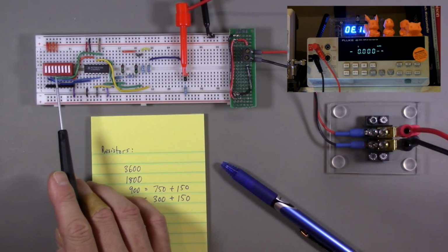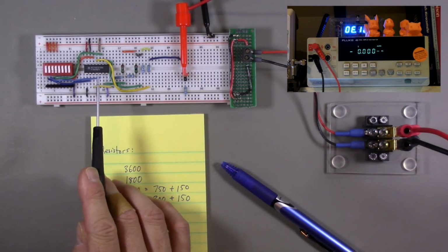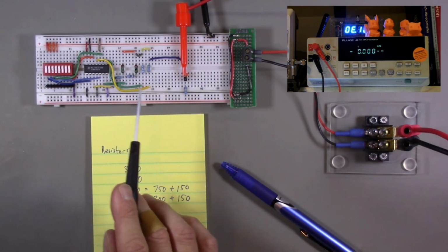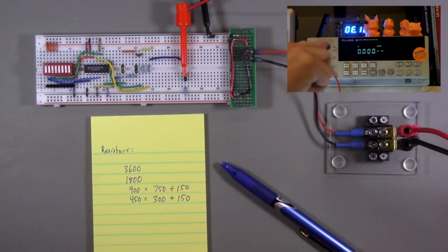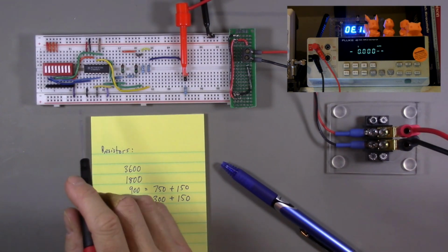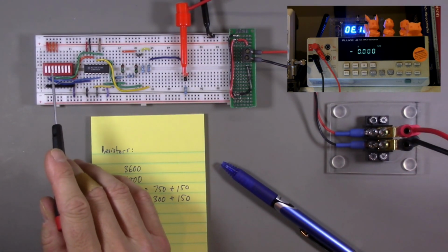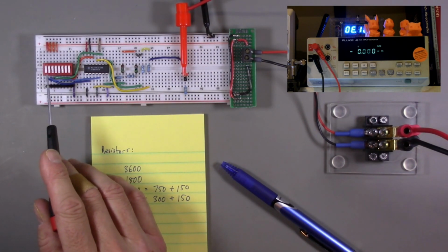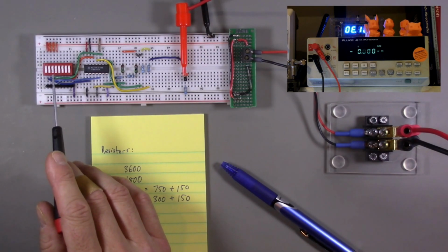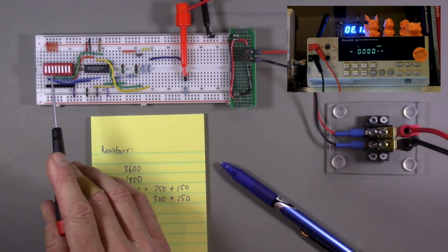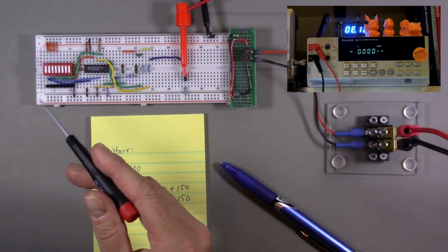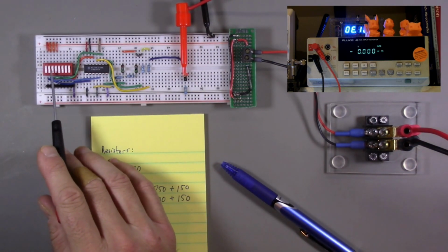And based on the combination of inputs and the combination of output voltages generated, I should get an output voltage here that I can read on our Fluke 45 multimeter here. And essentially what I'm looking for is that as I select various binary values here, I should see appropriate voltages generated, and by collecting some data, I can then put those in a spreadsheet, graph them, and make sure that I'm getting a pretty good linear series of voltages that correspond to the input values we select here.